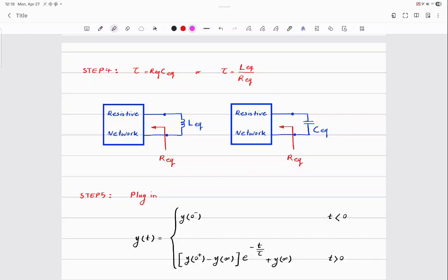And what do you need to do before your circuit analysis? Kill the independent sources. We already talked about that. Don't forget that. If you don't do it, you will get a different answer. Yes? So in every situation, we just kill the independent sources if you're trying to find resistance, I mean. Yes. Always. For equivalent resistance, always kill the independent sources.